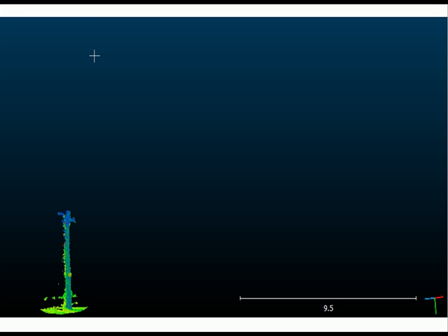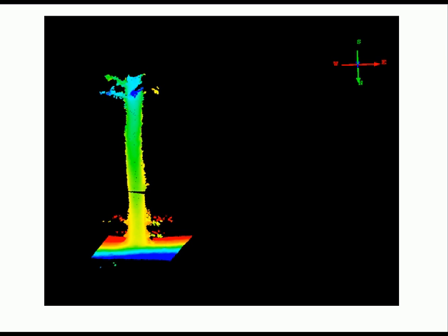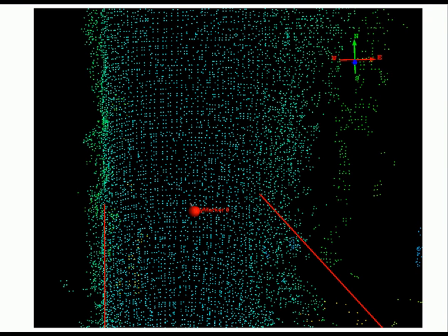So I converted these Cloud Compare files to an LAS and put them on Quick Terrain Reader, which has a better measuring tool for what we want to do. So here it is uploaded on Quick Terrain Reader, and I'd go up and mark at 1.4 meters, and then from there I would try and just measure from side to side. As you can see, you can tell pretty much the extent of where the tree would have been.